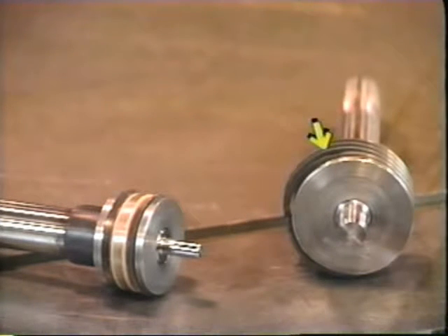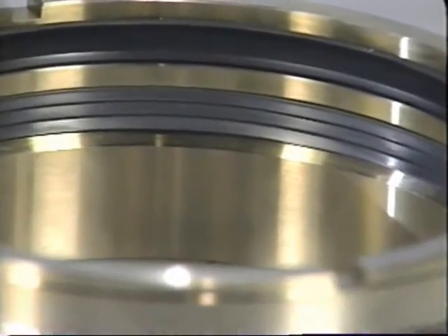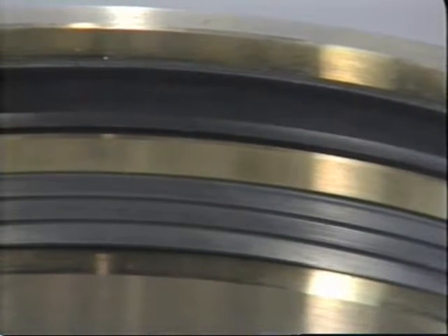Cast iron rings last longer but may allow unwanted leakage. Flexible seals may not last as long as cast iron but do form a positive seal. The seal on the rod, the gland seal, has two purposes: to prevent fluid from escaping and to prevent dirt from being carried into the cylinder as the rod retracts. A primary seal allows the rod to move through the cylinder body without allowing fluid to escape. A wiper seal cleans the rod, keeping dirt out of the cylinder. The space between the seals may be externally drained to prevent the accumulation of excess fluid.